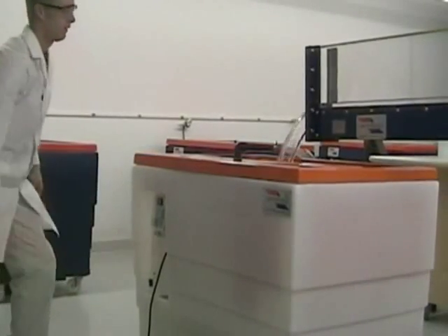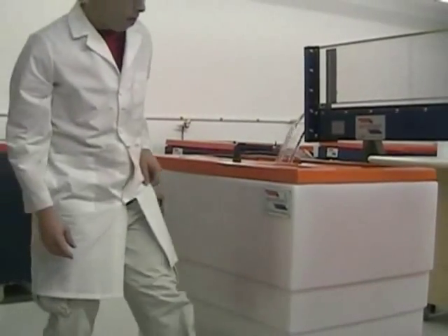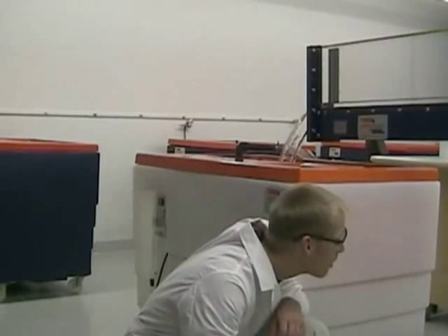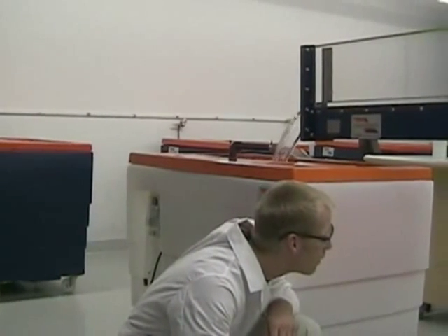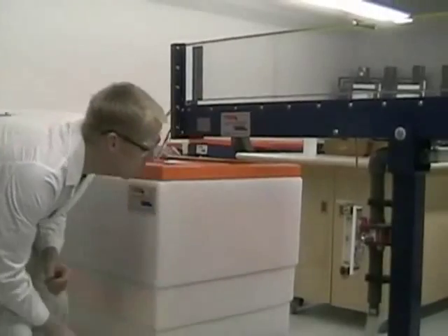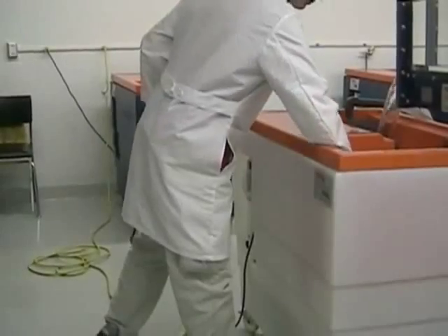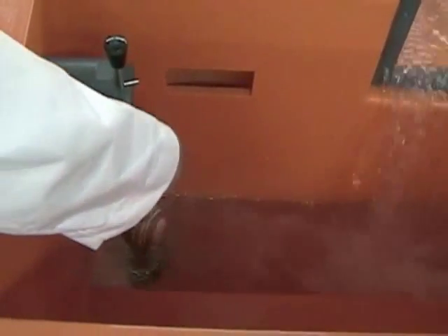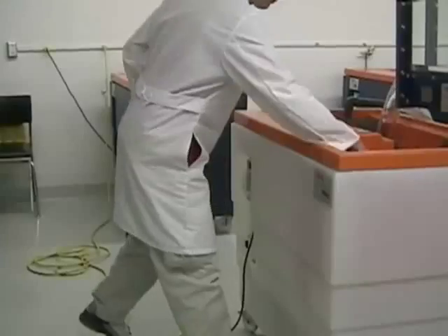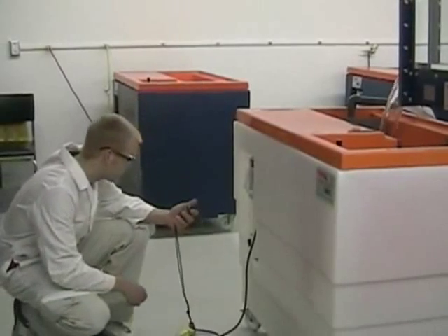The flow rate may be roughly adjusted to the desired flow rate by using the flow rate gauge below the end of the flume. For an accurate reading of the flow rate, use the hydraulic bench and stopwatch to read the volumetric change of water over a defined time interval.